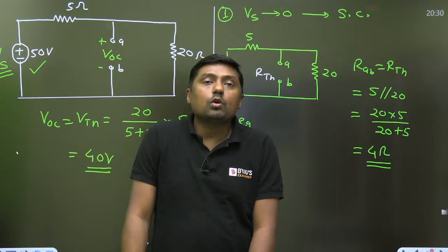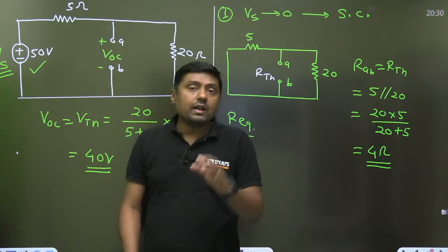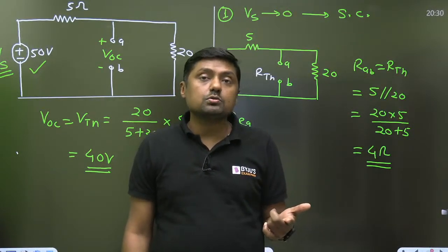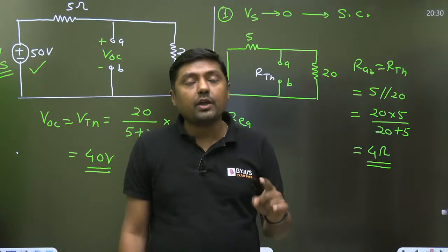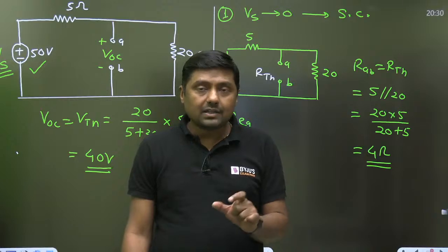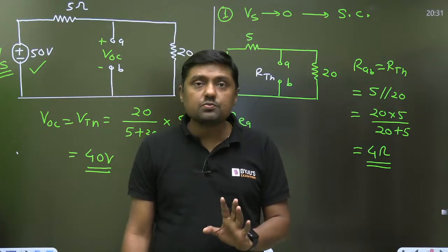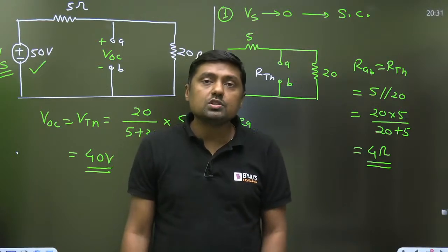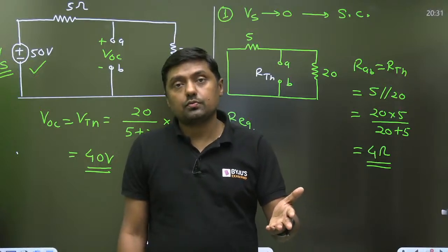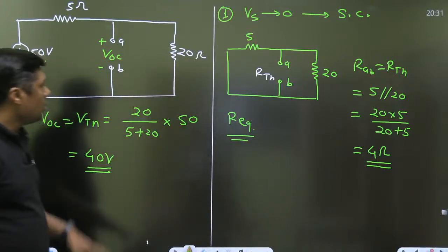Yes, Abhi, what is your question? So are current sources practically possible? No. Normally we have the voltage source, but we can convert that voltage into a current source by using a current mirror circuit, or a voltage to current converter. Practically, we have the battery as a voltage source. Voltage source is physically realizable, current source is not realizable. But we can convert the voltage into a current source using a voltage to current converter or current mirror circuit. These are the methods.